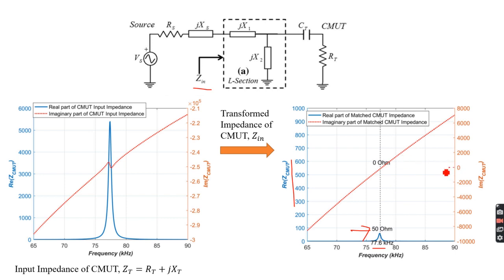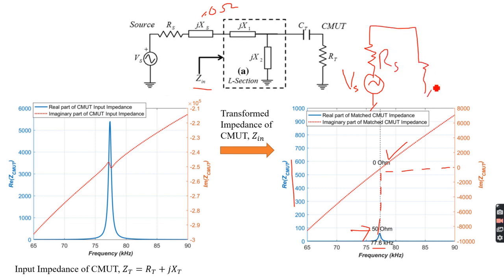And the imaginary part has gone to 0. Okay. So that's how it is, because we already set XS to 0 ohms, right? That was 0. So now the situation is that with the source or the driver or the generator, the RS has been matched to RL, and RL is again 50 ohms. That's how the generator is looking into it. So that's your Z in, right? So Z in looks like that. I mean, the generator sees the load as matched to its impedance.